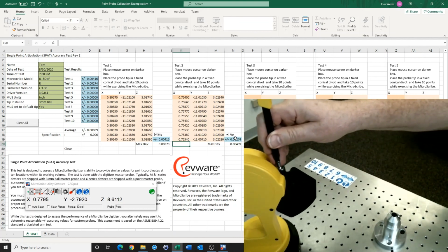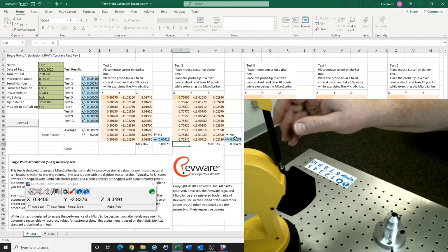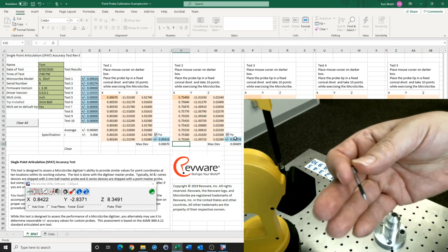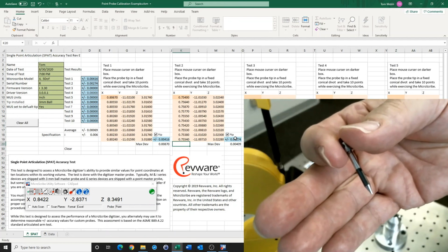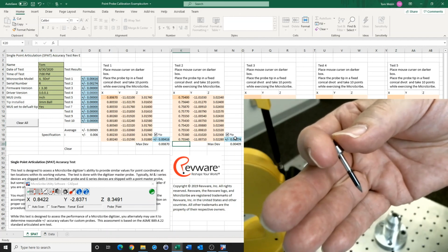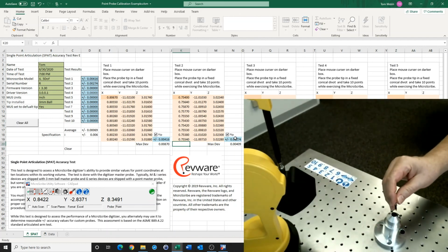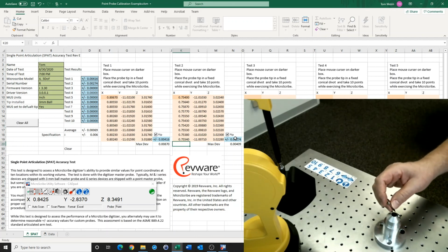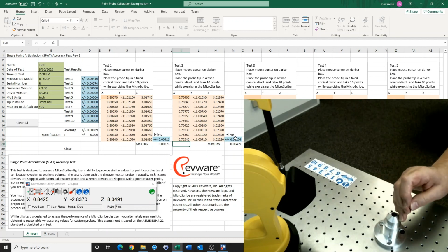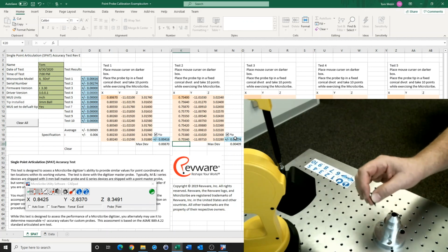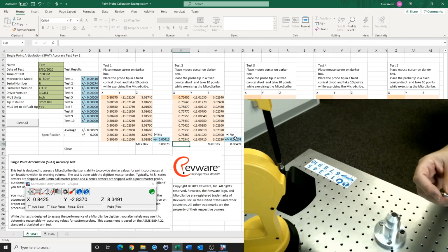And for those of you that really want to get down into some very fine work, these very small point probes have quite hard tips, and they will dig into just about anything quite easily. So using them, you're likely to scratch paint or metal surfaces. It'll easily put a mark on the aluminum.